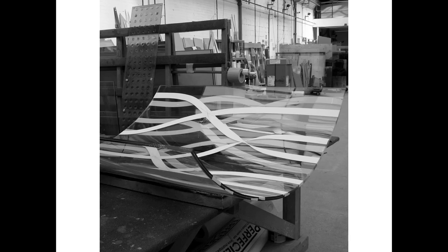I mentioned earlier this process of slumping. You will be familiar with the incredible geometric complexity that you can achieve by slumping glass, because you will have seen car windscreens, which take very complex three-dimensional shapes. The process of slumping is that in this case, as you can see, 2 layers have been bonded together, so it's a piece of laminated glass.